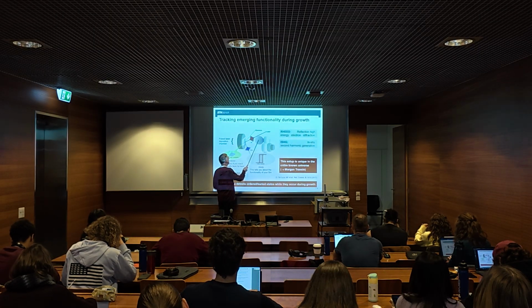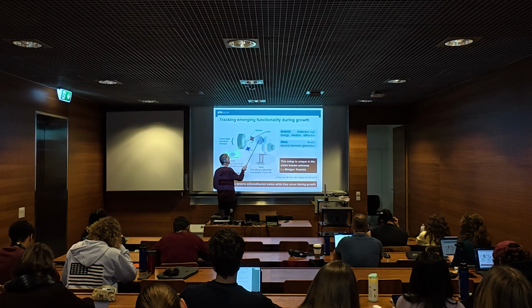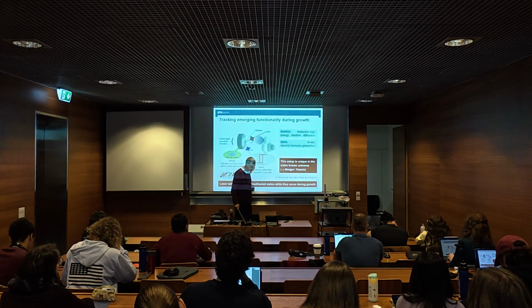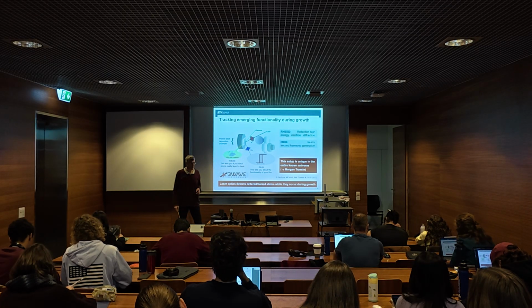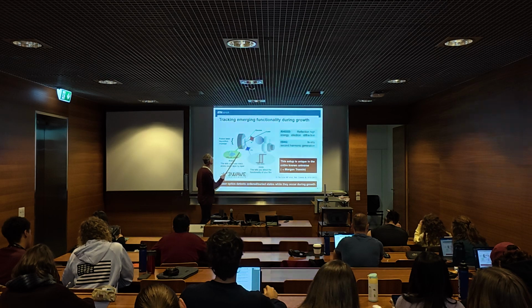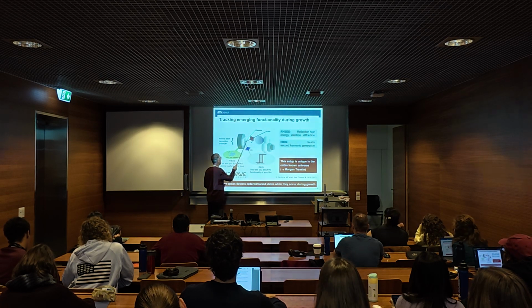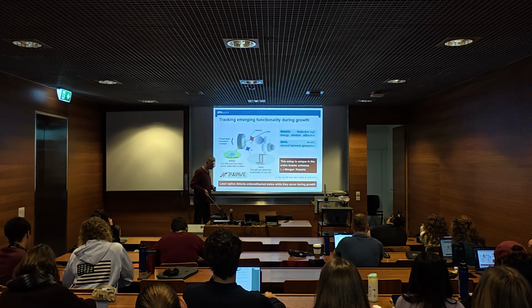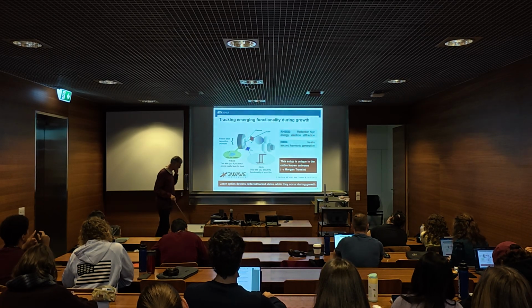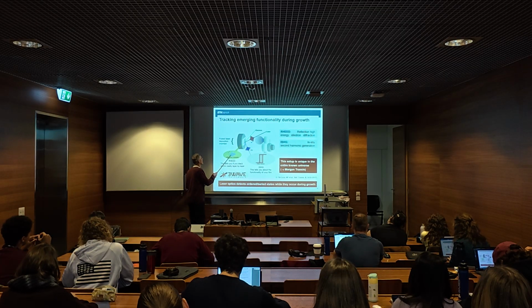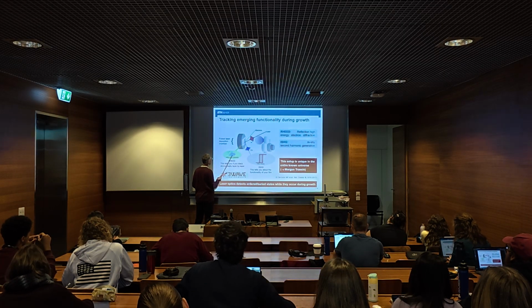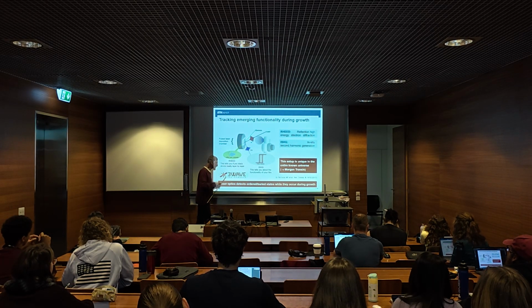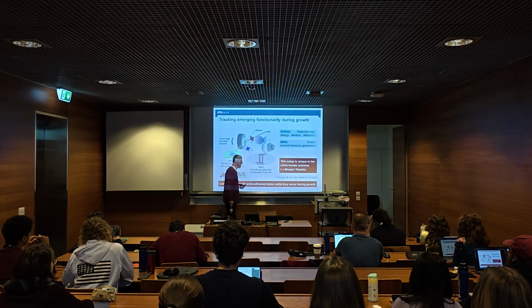So atomic fragments are shot off from this target, they fly through the vacuum, and they condense down on this substrate. If you do it under the right conditions, then it's not just stains that you get, but you really can make these atomic fragments arrange themselves into neat atomically crystallographic patterns, atomic layer by atomic layer. That technique is called pulsed laser deposition. Again, he's the expert in that.